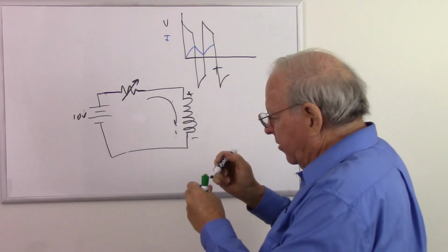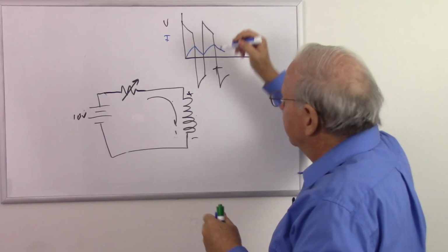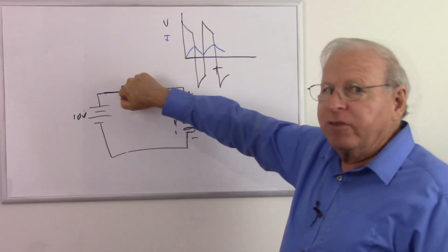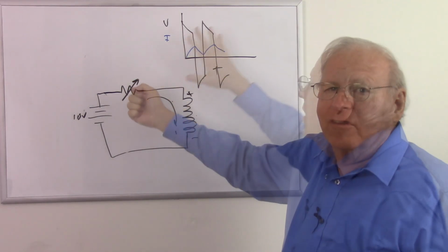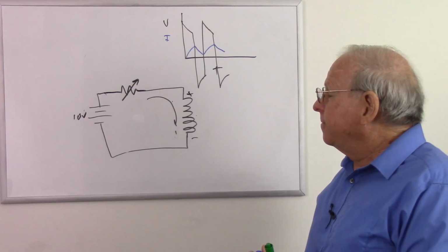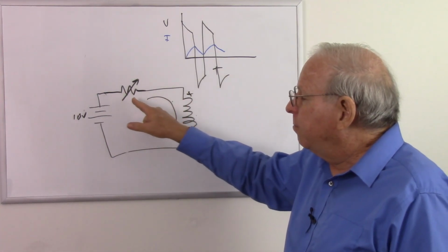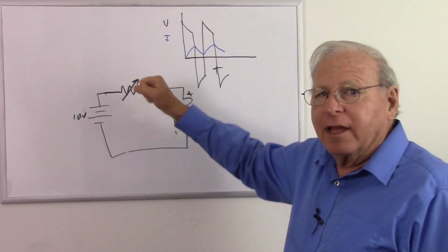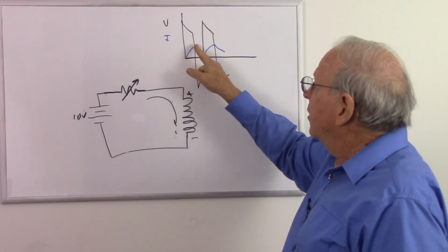So I'm getting exactly the same thing, except now instead of having those two switches, I simply have a resistance. Low resistance, high resistance. Low resistance, high resistance. And so I get the same effect by simply changing the resistance here. So now we're just one step away from making our oscillator. We just need a component that's going to periodically change its resistance in, how about in response to the current?